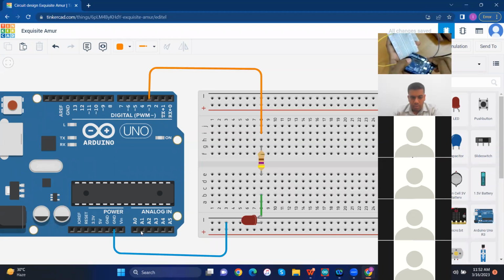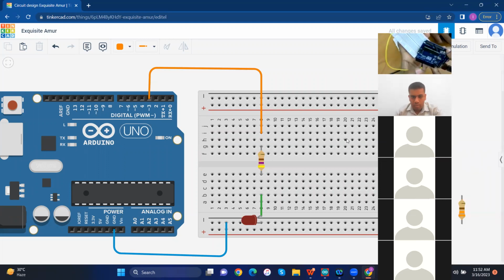Here you can see the analog pins, 6 of them, starting with 0. Because we are using digital programming, you can connect any digital pin. You can use an analog one also. I connected that to digital pin 6. Then you can use any digital pin there.